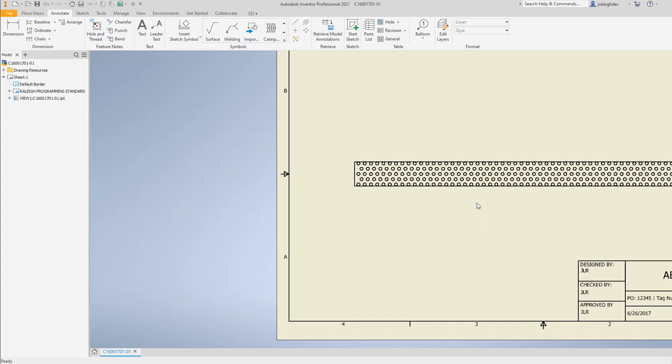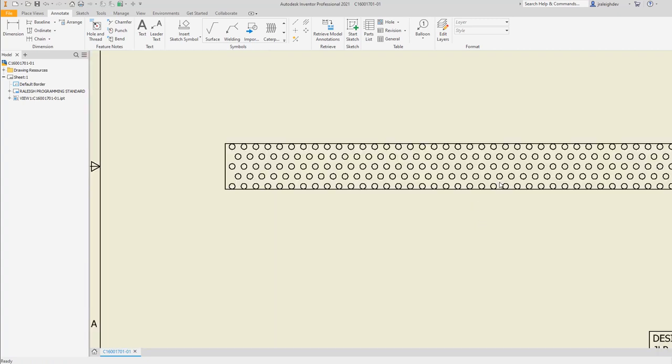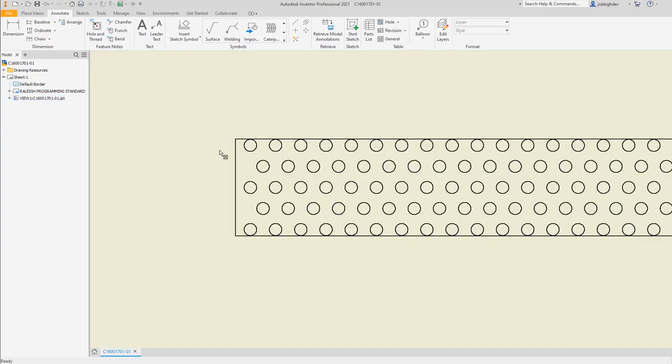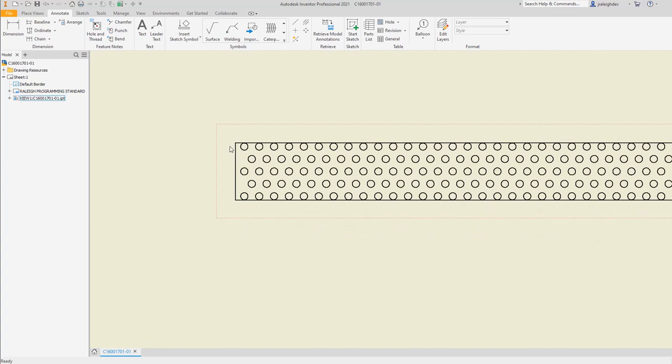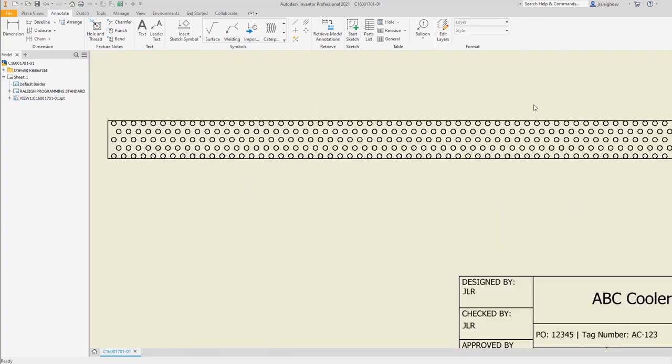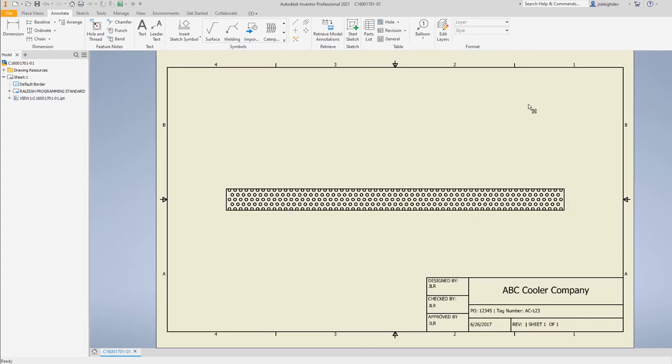What side of the view is the dimension going to be on? So are we going to be on the right side of the view, the left side of the view? Where do we want this dimension to be? Then we need to know if we need to offset the dimension any, if we need additional offset in case we have layers of dimensions. And do we need to pin any special text dimension like notes from the engineers or notes from the project manager, something like that? So we really need to be able to add all that in.